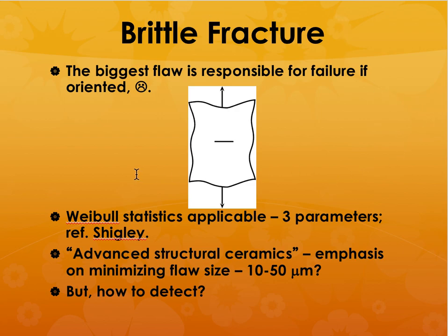And where is this statistics, where is this value going to be applicable? In design. So if you are going to be designing with an extremely brittle type of material, you have to take that into account when you are designing components made out of these kinds of materials. So you have to take into account the fact that your component might fail at say 10 KSI or at 50 KSI or at 90 KSI. Okay, so you have to take that into account because it will help you to define the lifetime of your component.